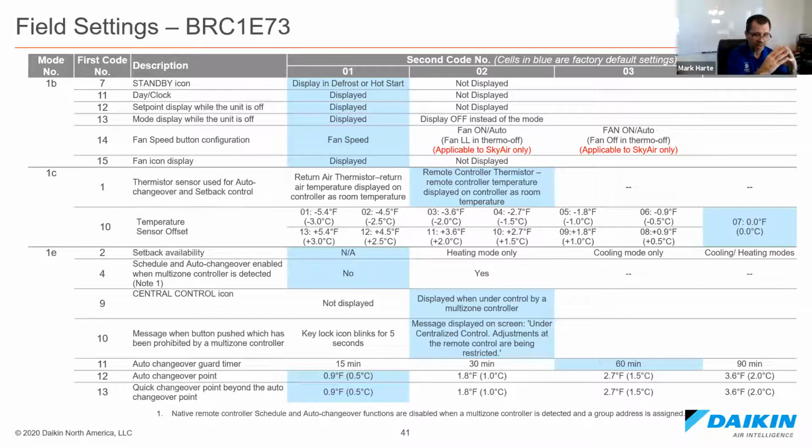Also, you can see each fan coil has a liquid line sensor, a gas line sensor. All of them have return air sensors except for the vertical air handler that has no return air sensor, and the CXTQ, that coil I showed you that went on top of the furnaces. All the others have return air sensors. We can see those 3 sensors from the controller.